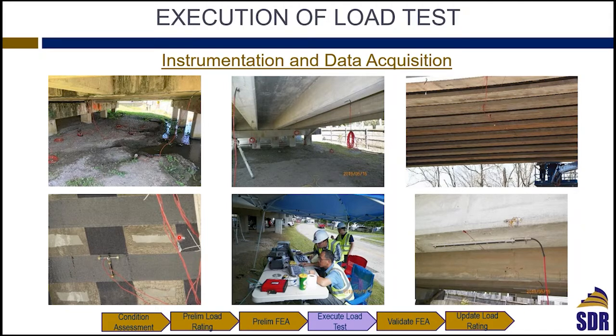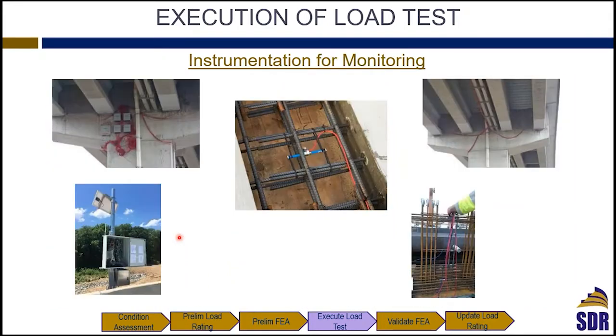Definitely this instrumentation, the pictures look nice, but there are a lot of challenges out in the field. In those pictures, yes, we can be standing on the ground and access the spans to be tested. For some other spans, we have to be sitting in a boat doing that. It could be in a snooper truck, or in a man lift, and there are a lot of challenges to do the instrumentation, like how to access the bridge and when you can access the bridge. If you're working on a swing span bridge, which means they can open the bridge while you're working, you have to secure all your wires. So there are some challenges that come with the instrumentation as well.